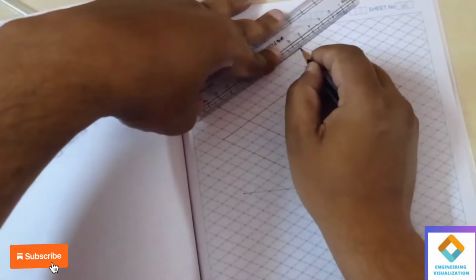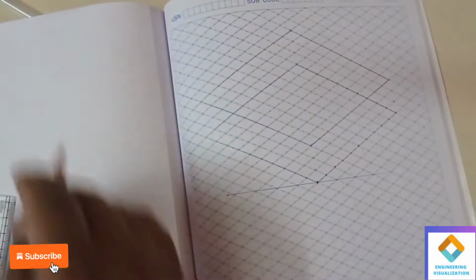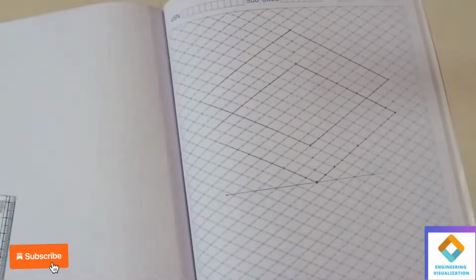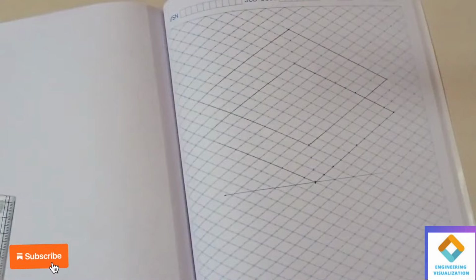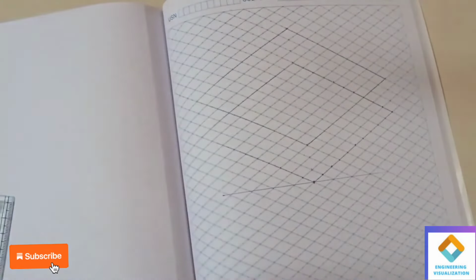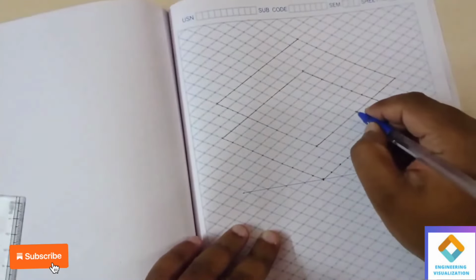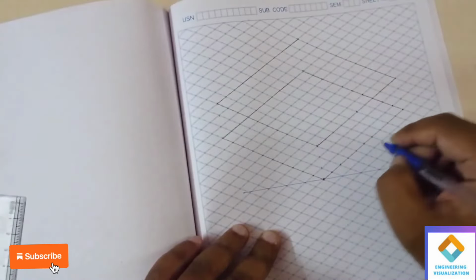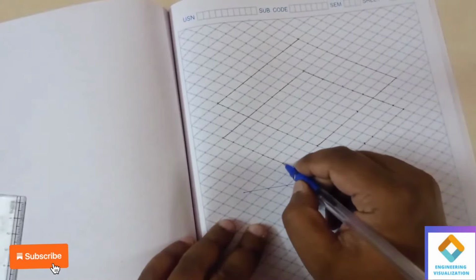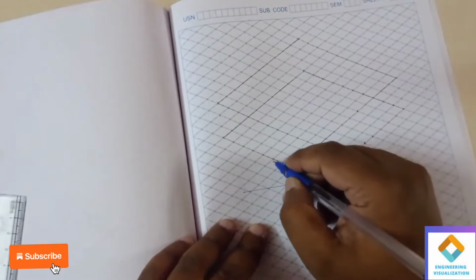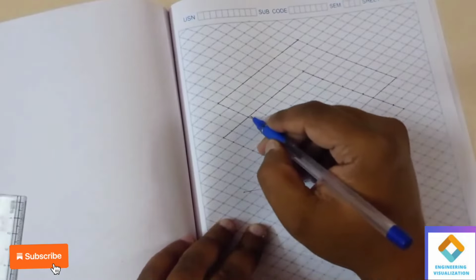After constructing this box of 10 by 10, we should construct the ellipse here. Two ellipses we have to construct, and then we have to join them to construct the cylinder here, the cylindrical slab. So use the compass. First we should mark the middle point of all these boxes. Mark the middle points for both the top box and the bottom box. You should mark exactly at the 5. Midpoint we should mark.